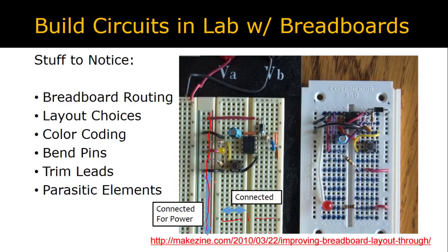What this means is that your choices when you design a breadboard circuit really matter for your experience of working with that circuit. Make sure that you build your circuit carefully, and especially try to minimize crossovers and cross-unders, which deeply undermine your ability to work with the circuit. You can get some additional clarity in a circuit by color-coding wires. For instance, the red and black wires in both circuits tend to convey special meaning about power supplies.